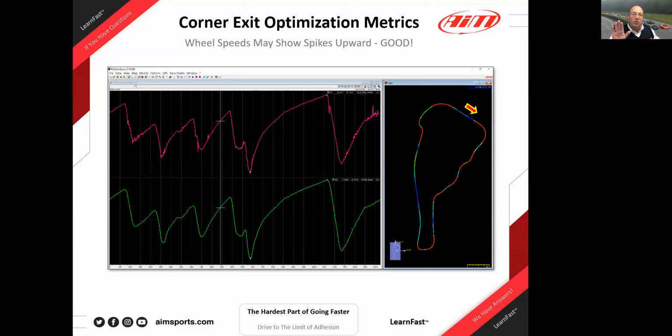They apply the throttle only as fast as they think that the car will accept the control input. They never push the pedal early enough or get to wide open throttle soon enough for the car to begin to lose traction, especially talking about big high horsepower rear wheel drive or mid-engine GT cars, which is this car.